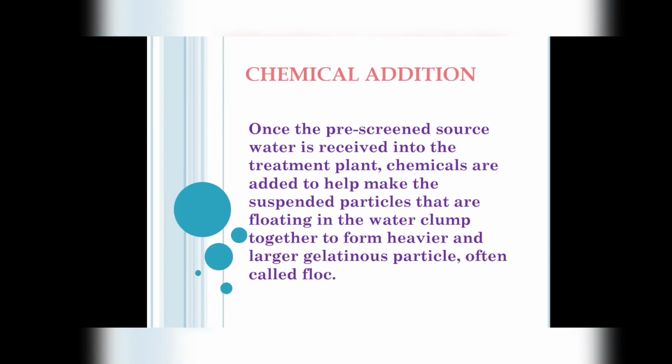Chemical addition: once the pre-screened source water is received into the treatment plant, chemicals are added to help make the suspended particles that are floating in the water clump together to form heavier and larger gelatinous particles, often called floc.